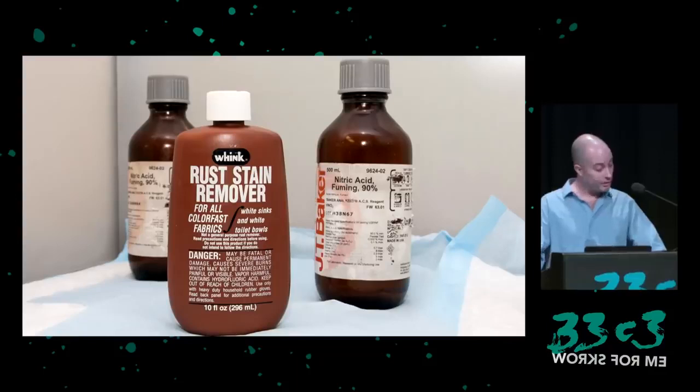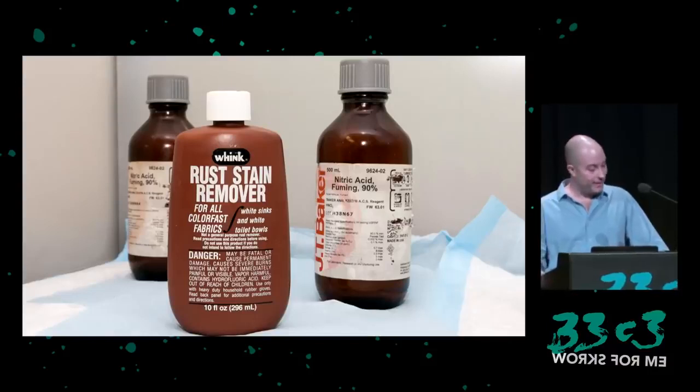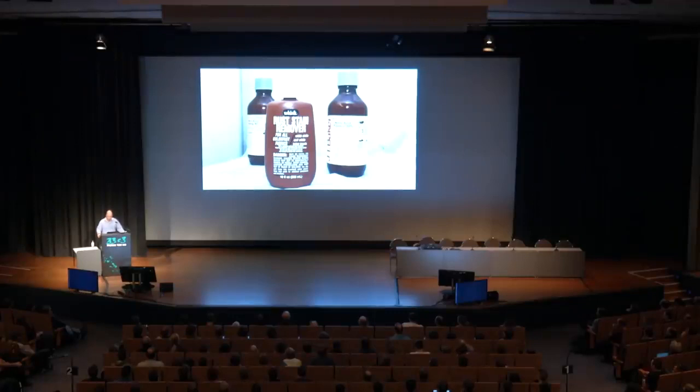The etching result isn't perfect. Some parts of the chip will be etched deeper than other parts, but I've gotten quite useful results using this technique. You really don't want to breathe in these fumes, so do this in a fume hood, in your garage also.